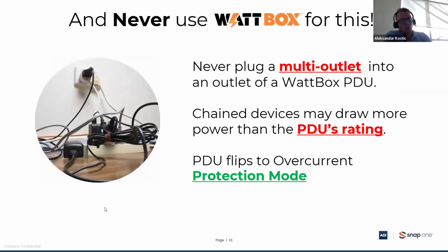Also, a WattBox shouldn't be connected in a daisy chain. So we always need to connect end devices to the WattBox and not daisy chain by connecting one WattBox to another, because that can easily cause overload and the WattBox can flip to protection mode with overcurrent.